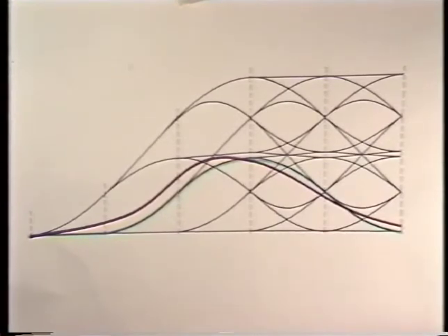This is the phase trellis as it evolves from one particular state. The red curve is a received curve, and the green is a correct signal. All possible phase paths are shown with black color in this figure. Note the periodic structure of the trellis. Each part between the dotted lines corresponds to one symbol duration. After some time, these will repeat.